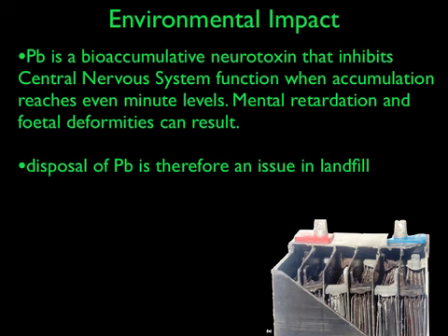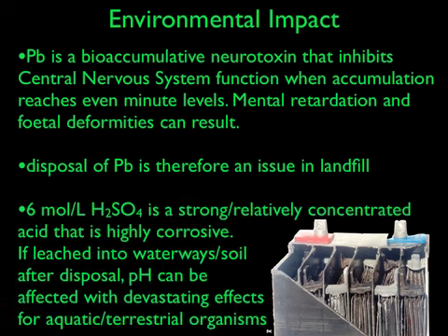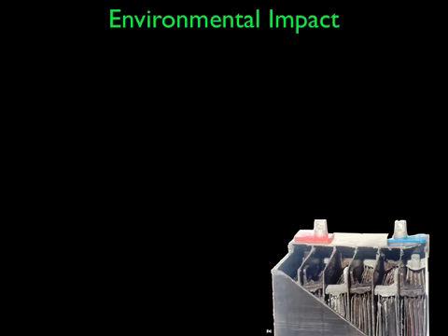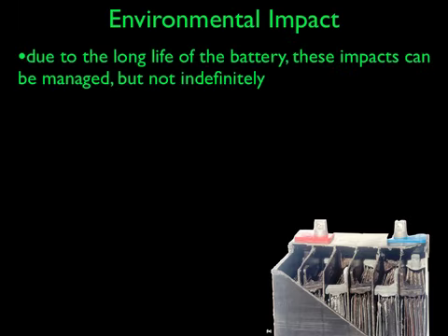The disposal of these batteries, therefore, is an issue for landfill, and they ought not to be disposed in landfill because there's a risk of leaching into the environment. Likewise, the sulfuric acid is a strong and concentrated acid that's highly corrosive. If that's leached into waterways after disposal, the pH can be lowered, which can have drastic effects on soil pH and water-dwelling organisms. So again, the sulfuric acid electrolyte must be monitored during disposal.